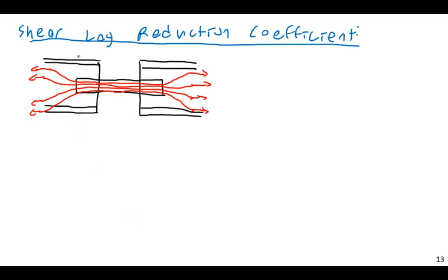Look at this. Stress does not just instantly move. It takes a certain distance for the stress to become concentrated. So right at the intersection here, this part and this part of the wide flange shape is carrying little to no stress. All of the stress, before it can enter the bolt holes and be transferred to the connecting element, first in the W shape itself has to be concentrated so it can flow into here.